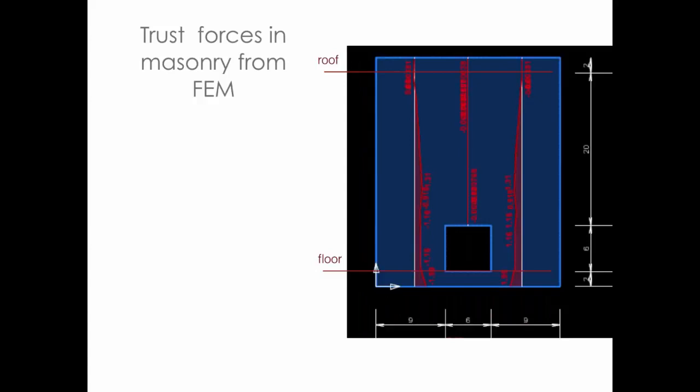And these are like one kip. These are like a small value of thrust load. You can see them actually developing quite a bit up within the wall, right? It's not just right at the opening. Suddenly, boom, some thrust load gets shot out from the lintel, right? It does get collected all the way up the wall. There's some arching going on throughout the wall panel. It just doesn't just happen at the bottom,